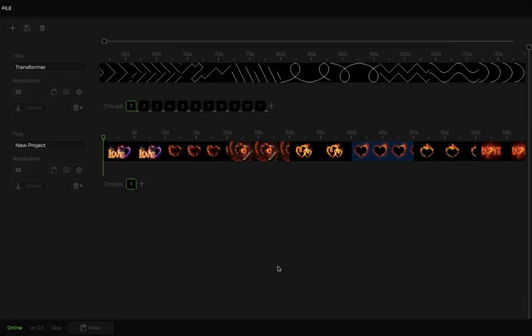With props with microcontroller board version 1.4, you have to connect the USB cable to the device and turn it on. There are only 5 groups available to upload. You can upload the project with 11 groups, but only 5 will display on a prop.